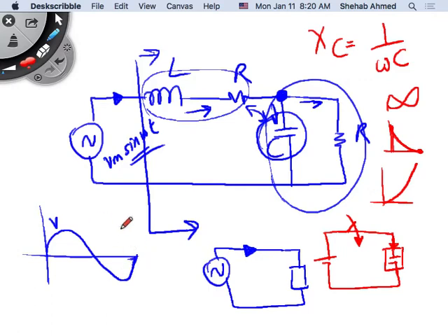Yeah. In AC circuits, though, if the voltage is sinusoidal and the impedance is a passive, linear impedance, then the current will also be sinusoidal. Okay, so let's agree to that. So if they're both sinusoidal, something else is happening to the current in the circuit where the equivalent impedance is capacitive. What will the current look like? Will the current look like this? It will be what? It will lead.